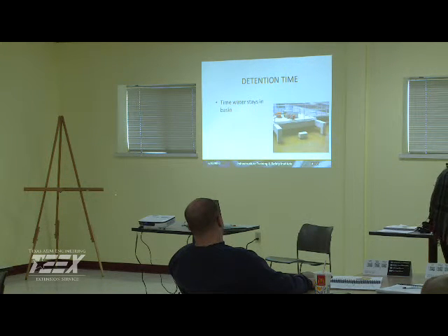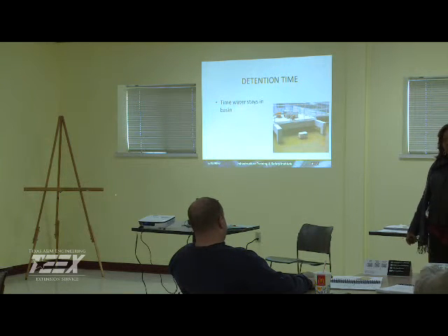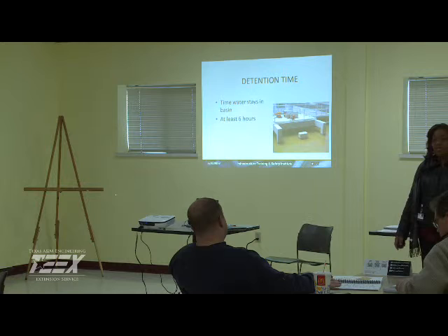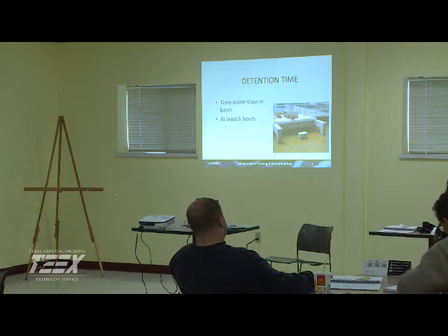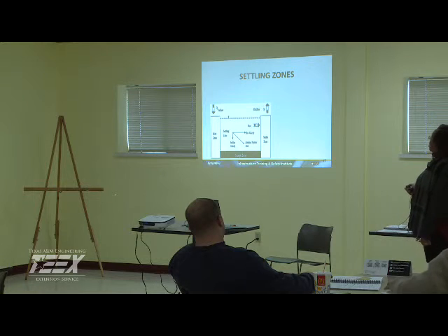All right, we talked about detention time. Detention time is the amount of time that the water resides in a particular basin, flows through that basin, or is retained in the basin. For our sedimentation basin, a minimum of 6 hours is what we're looking at as a requirement.